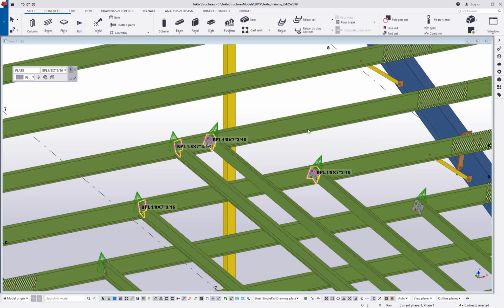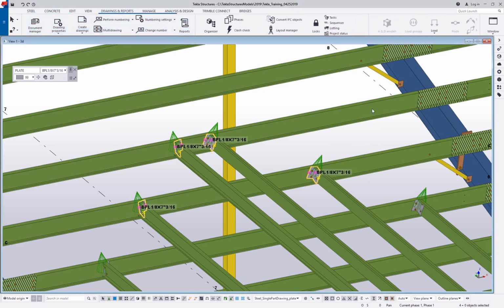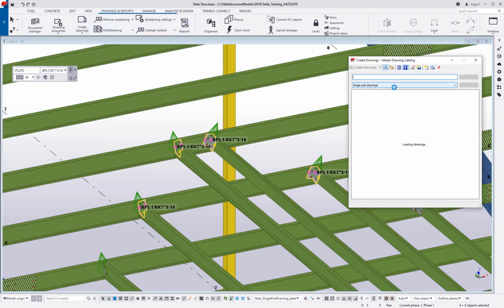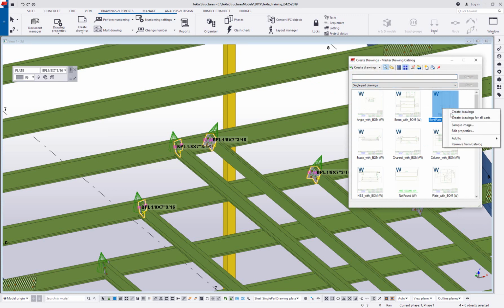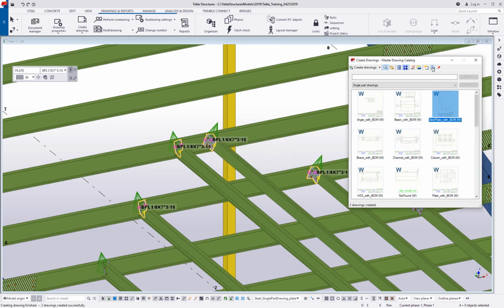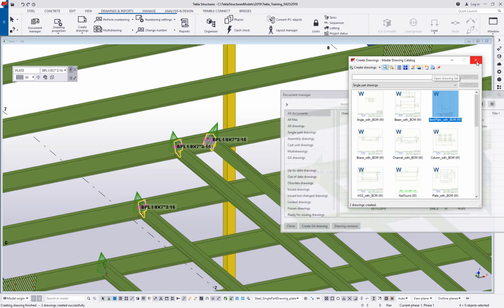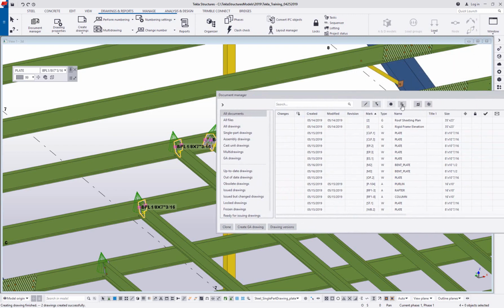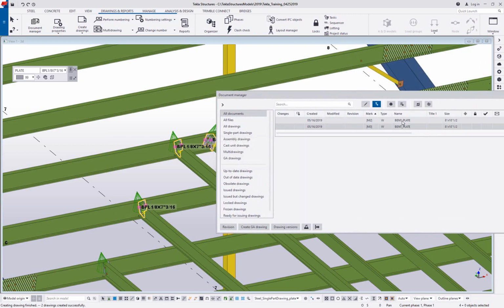The same is true for any bent or folded plate. There are drawing settings available that will automatically go ahead and unfold those for us flat. Also, any CNC files that you would make of these plates are unfolded flat for fabrication purposes. Just to give you a look at what those single part drawings look like for these guys.